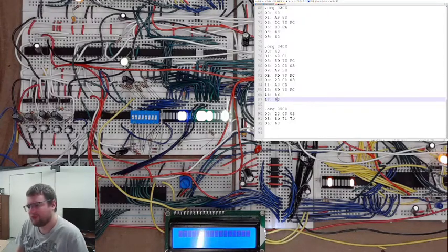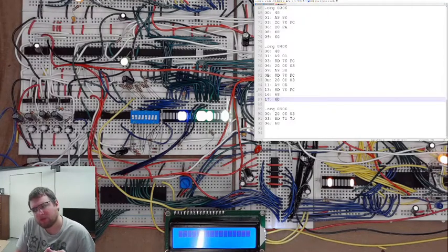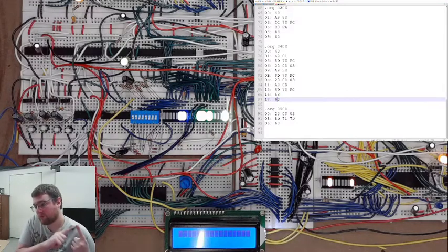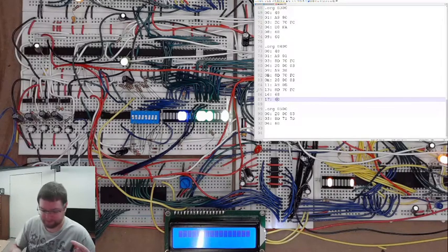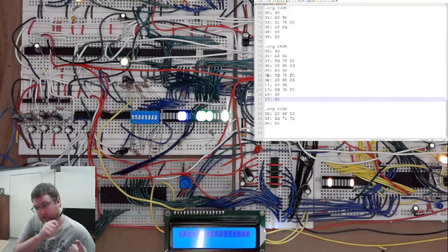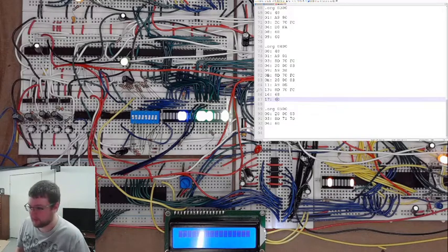And I don't know which one you should check. You should check the last one. Because if you read from the ROM while it's writing, it gives you the inverse version, which means the inverted version, you know, the not version. It inverts all the bits of whatever you last wrote. And so you should check the last one to see when you finally read the thing that you expected to be there. Because it should be the last thing written.